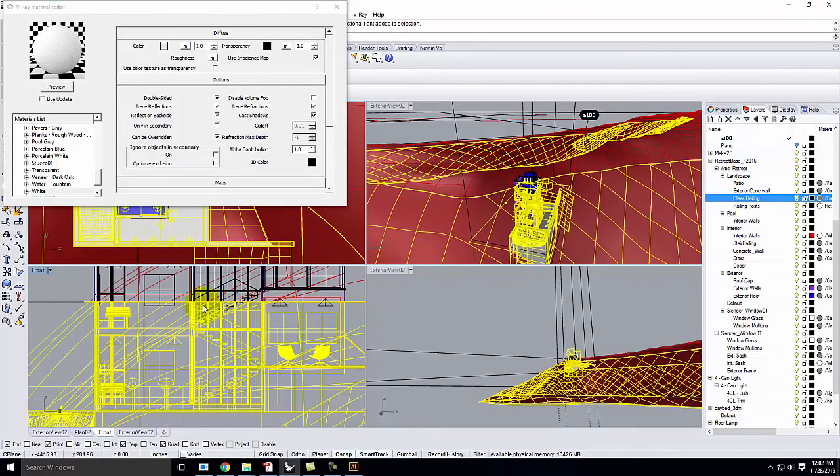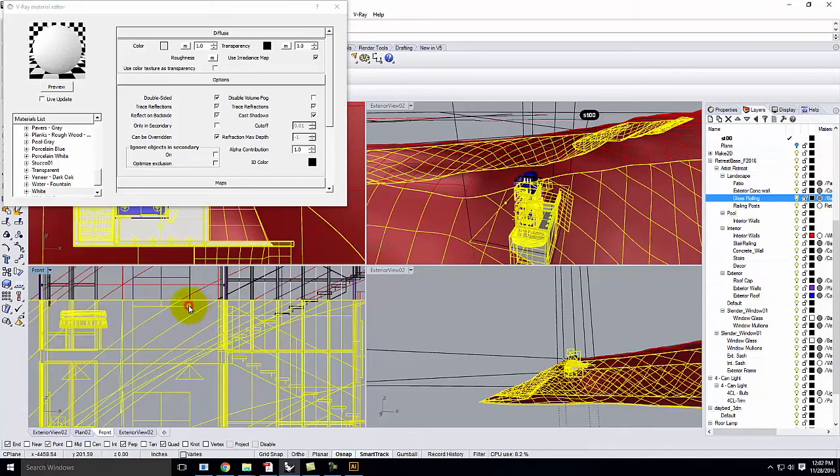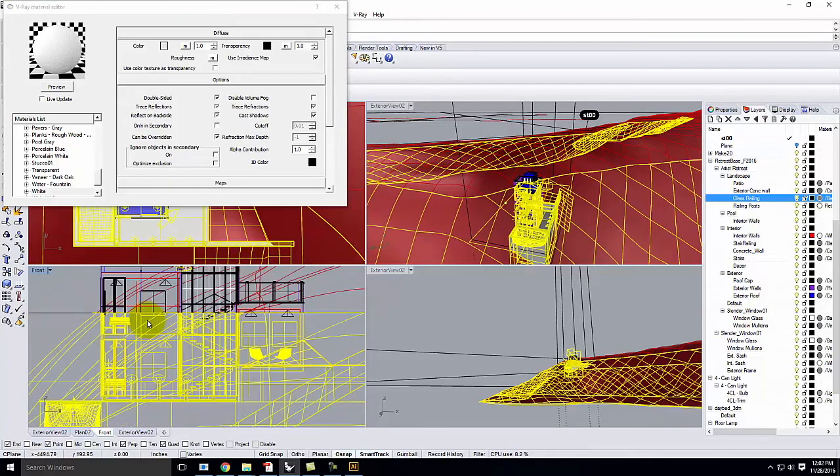All right, so I should have everything below. Looks like I need that piece as well. Now that I have everything below, I'm going to apply this white material, except, once again, for the glass. So we'll turn off the glass railing. We'll turn off the window glass. We'll turn off the window glass here as well. So all of the glass is deselected.